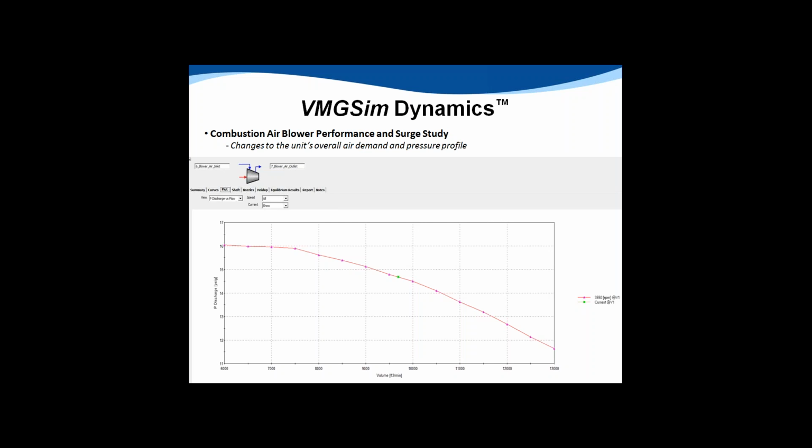If we're operating at a point that's so low, is that blower now surging? From a control and reliability standpoint, we don't want that to be our new operating point under these new operating regimes or turndown conditions.